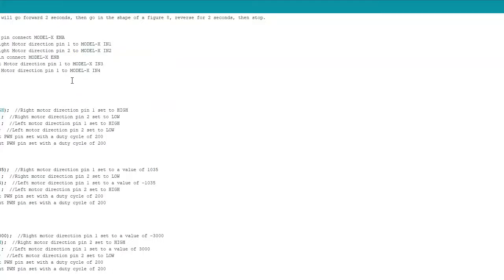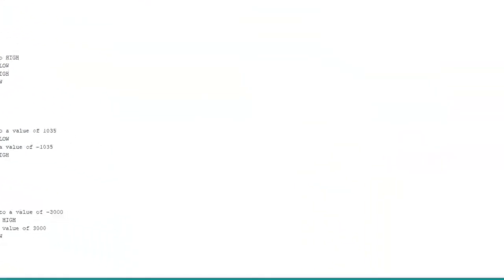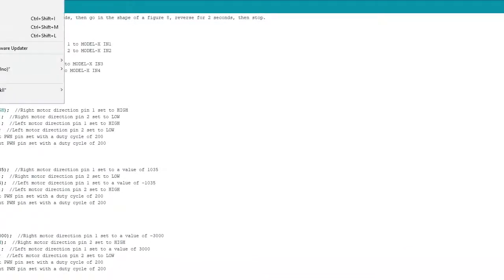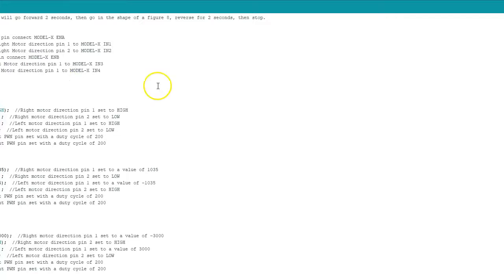All right, in order for your computer to communicate and send data and information back and forth, it has to be on a communication port. Okay, so right here, in the same spot, it shows communication port 11. Okay, as long as you're on COM port 3 or higher, you'll be fine. But if you needed to change that, you would go back to Tools. You would go to Port, serial ports, because this is a serial port, and you would click communication port 11, and then you would see down here which communication port you're on.